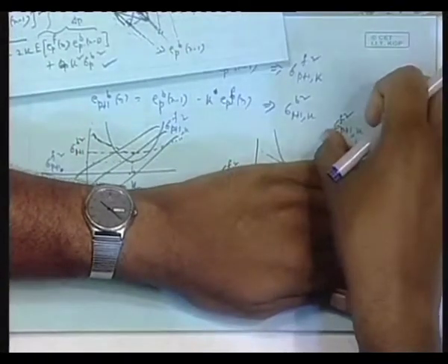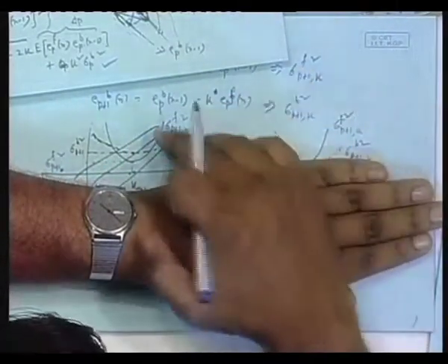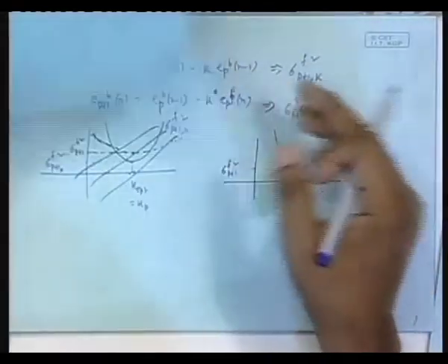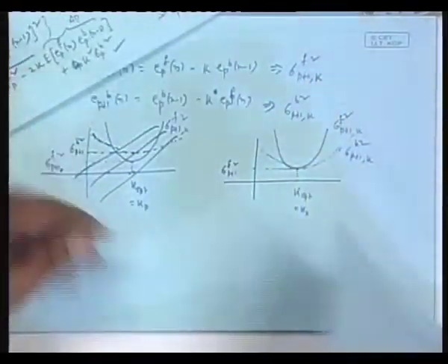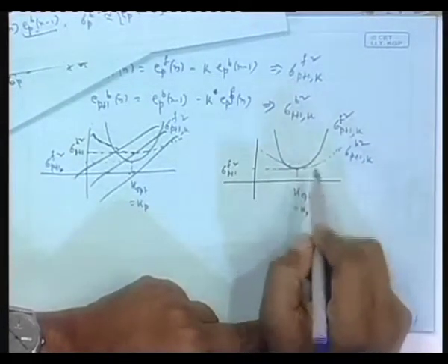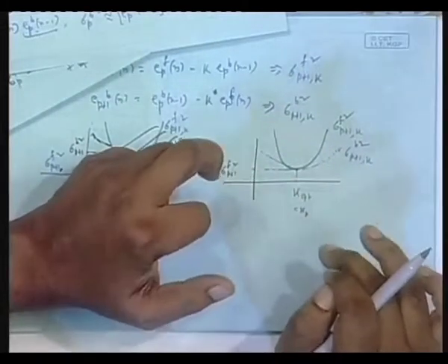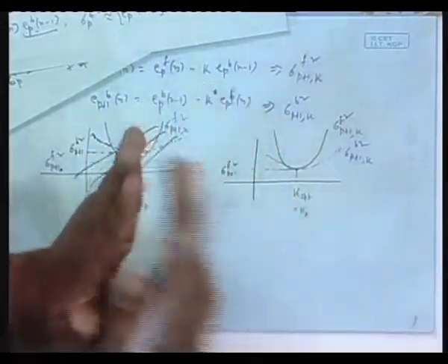I considered this, and on this I did steepest descent and then the LMS approximation. I got one recursive equation for Kn, as I did that time. But alternatively, you can do it on this also. You get another recursive equation for Kn, and there is no guarantee that the two k sequences will, at least after convergence, be the same.